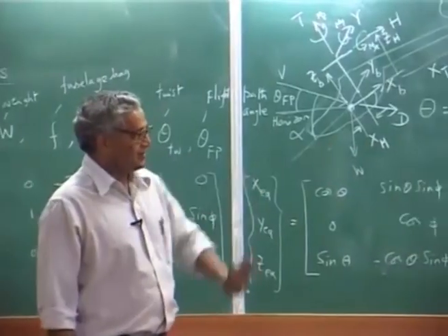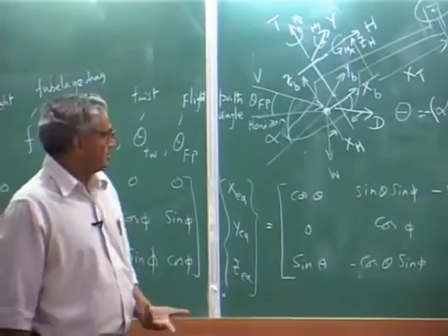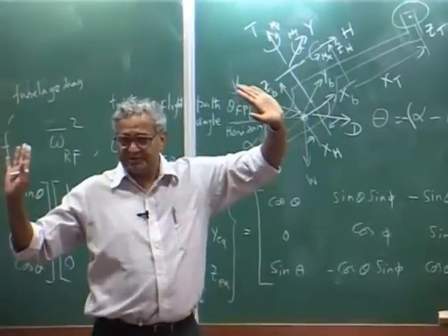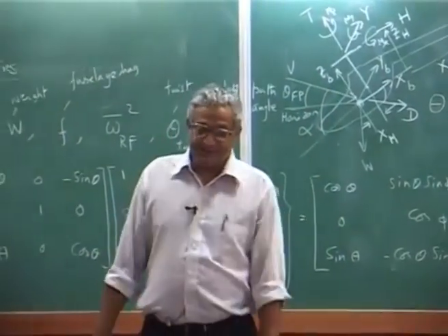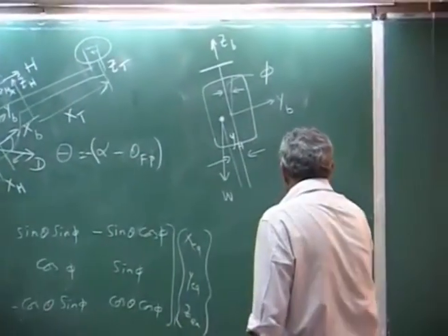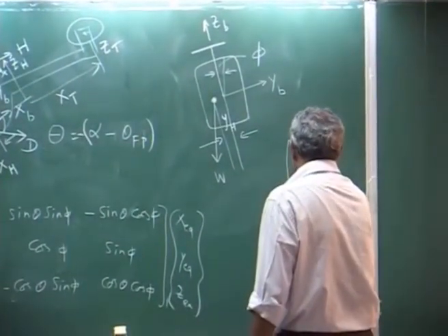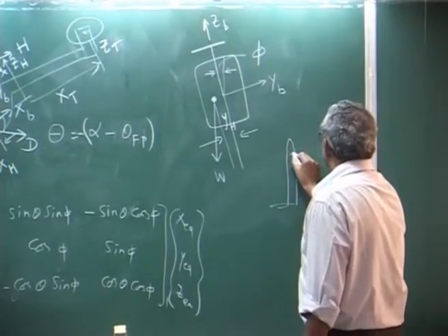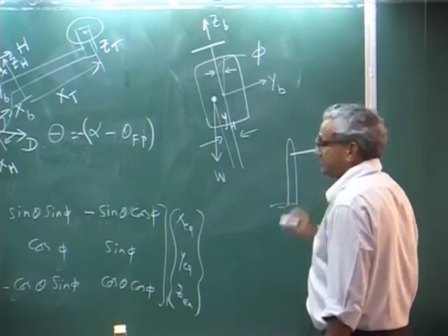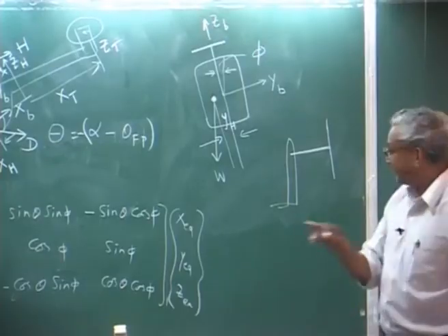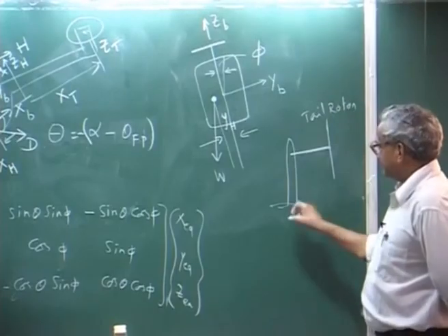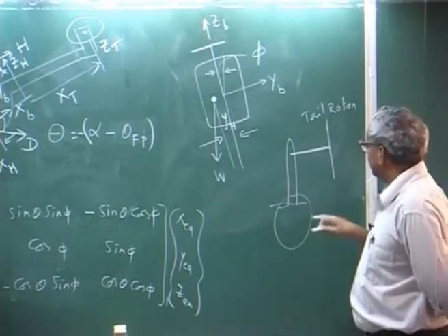Now, you have the vertical force equation. Similarly, for the horizontal force you have the hub load, because for the tail rotor you say it is not giving any vertical force. Sometimes in the design the tail rotor fin may be tilted, looking from the back, with the fuselage going forward.